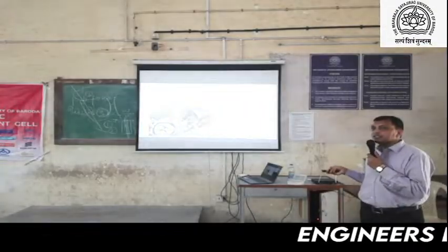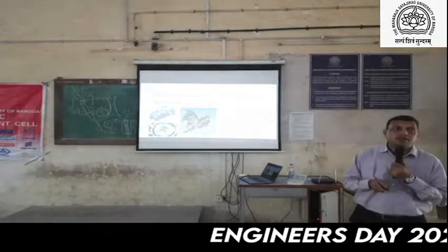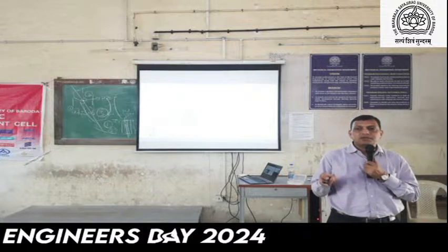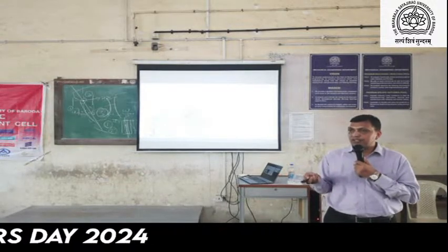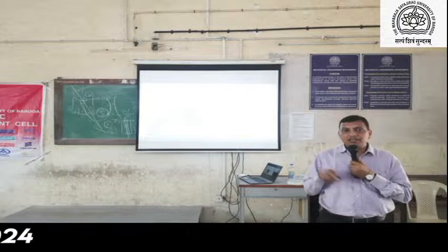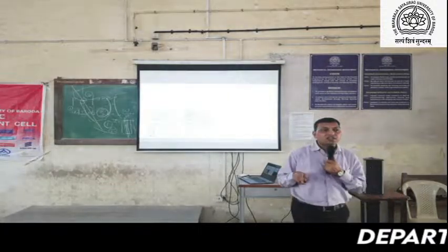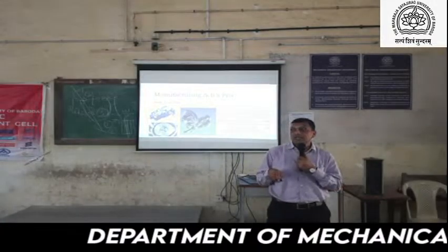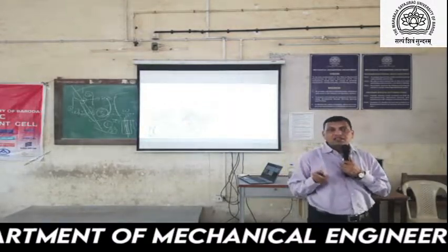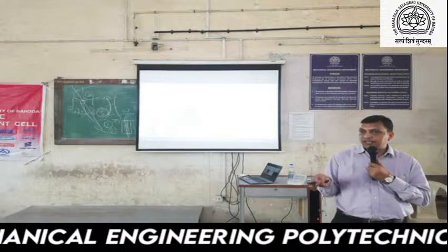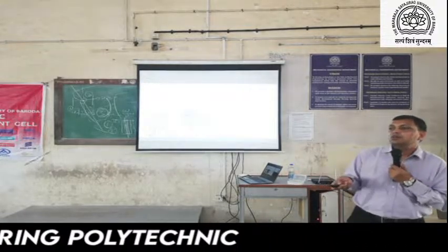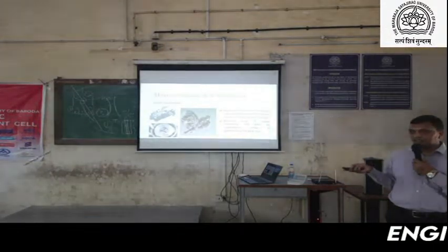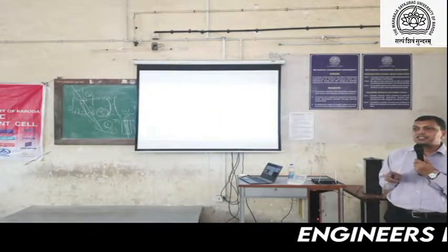Now, what is axial plane and radial plane? Radial plane is already defined in particular bearings. We can consider the ball bearing, cylindrical bearing, spherical bearing. But for taper roller bearing, there is no value given in any catalog of the bearing manufacturer, so we have to maintain it in our assembly. If we consider the spherical bearing or ball bearing, the clearance detail is already given, so we don't require any change.